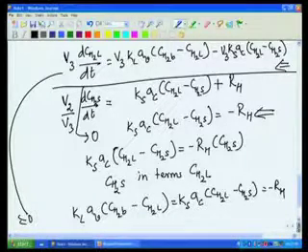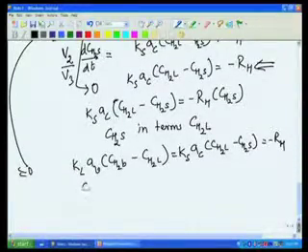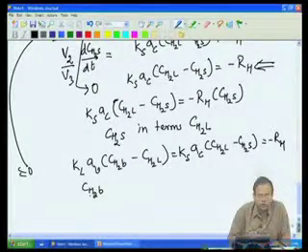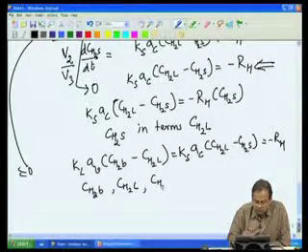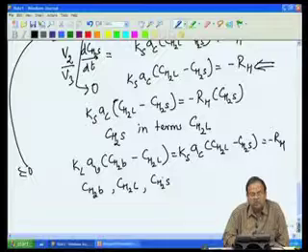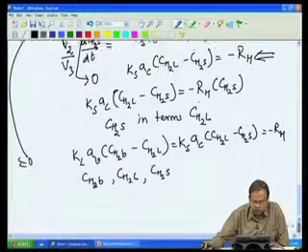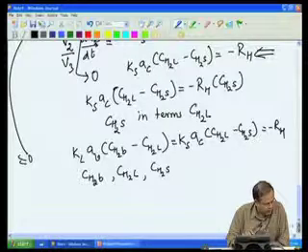So, from these two balances we have two relationships. We have three concentrations of hydrogen. The bulk concentration will be determined by the partial pressure of hydrogen. Then we have CH2L and we have CH2S, that is on the surface. So, in the gas phase, liquid phase and on the surface, we have three concentrations, and we can use these relationships to eliminate one in terms of the other.